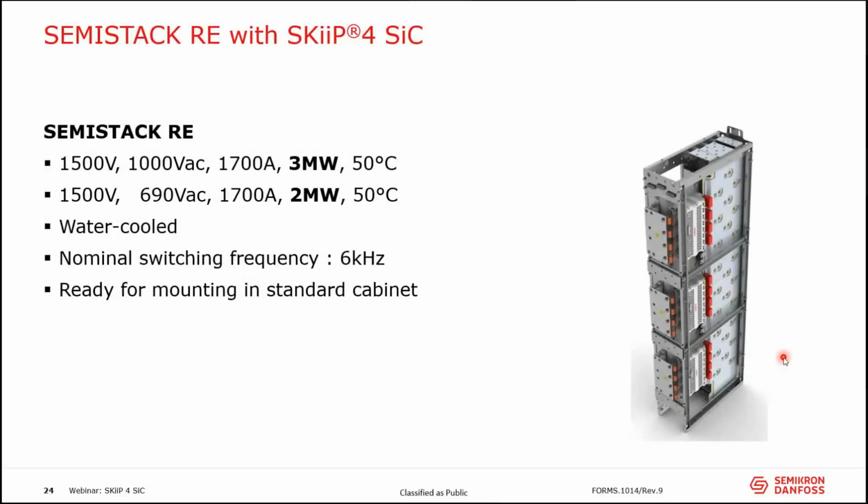So in general, we also can order the SemiStack RE, that is a stack where you can order the SKiiPs together with DC link and AC connection already in one stack. This is available for 3 megawatt and 2 megawatt solutions for different voltage levels. It is water cooled, and the power rating is made for 6 kilohertz, but in general also other frequencies can be discussed.